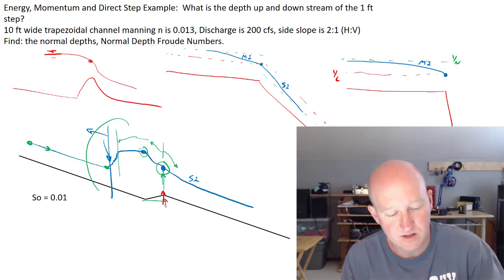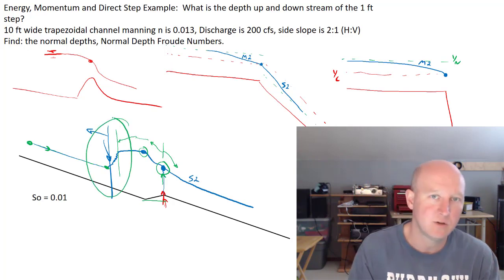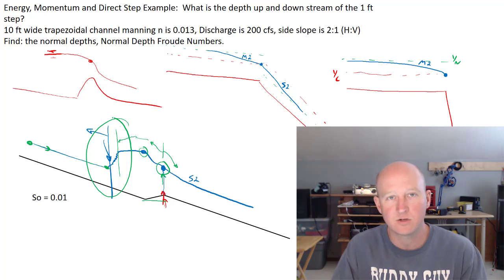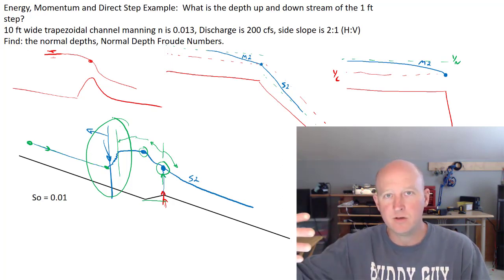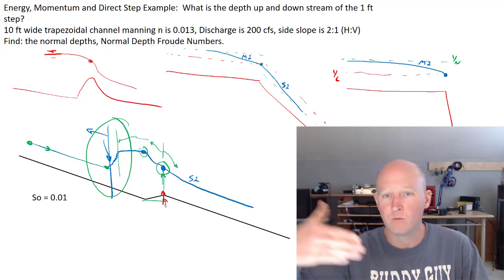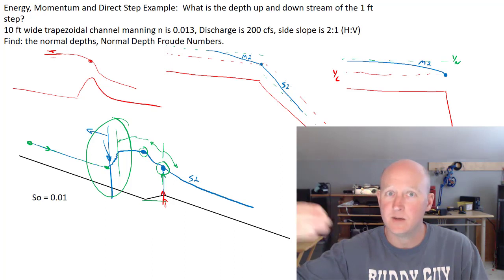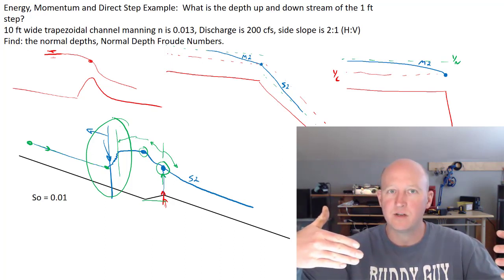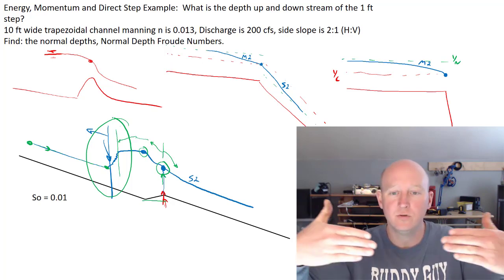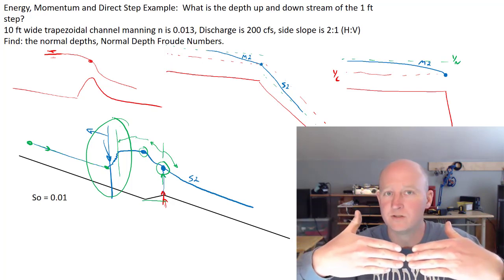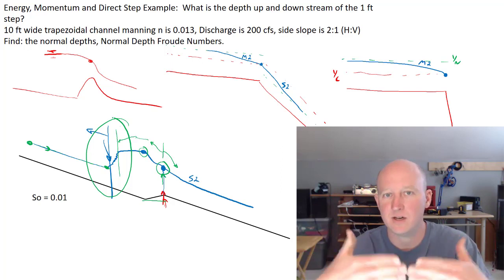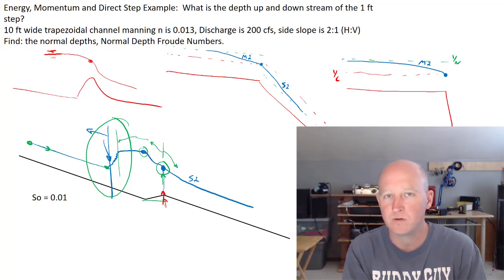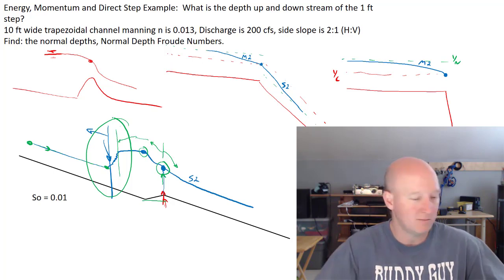And so a hydraulic jump is actually a location where there's a conflict of controls. Upstream, we've got supercritical water racing down. It's upstream controls. And then downstream, we've got subcritical water that's downstream controls. And so those two directions control the water surface depth until you have the hydraulic jump. So that's one of the tricks that it takes a while to get used to, and really that's the reason that we're going to do just a ton of examples.